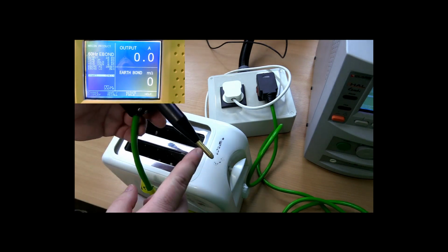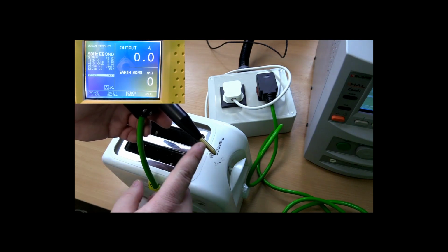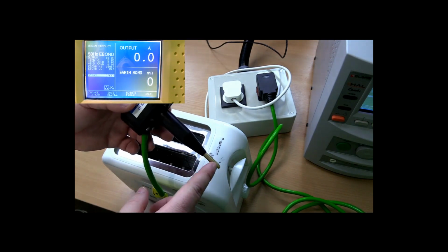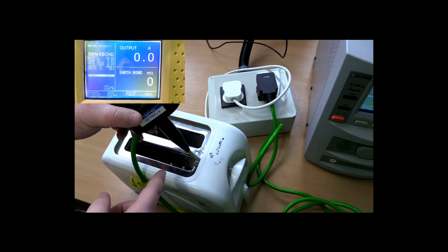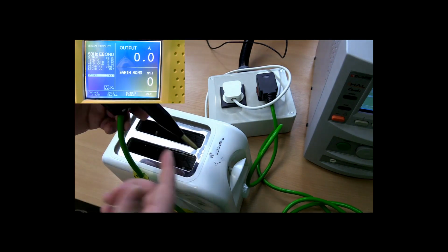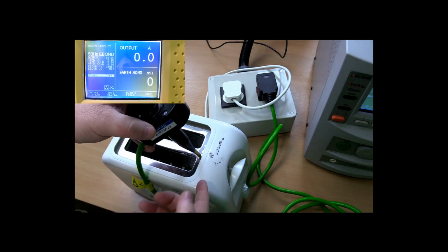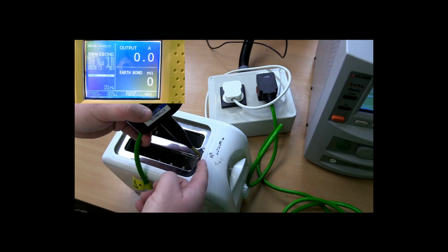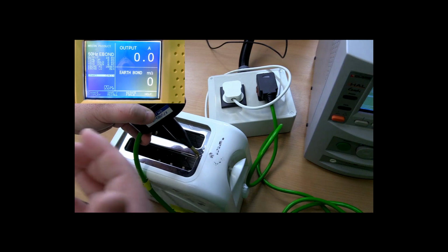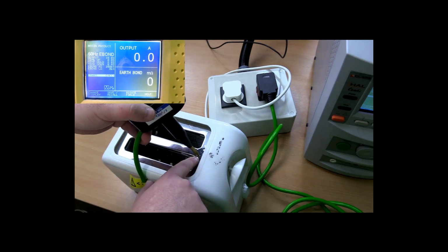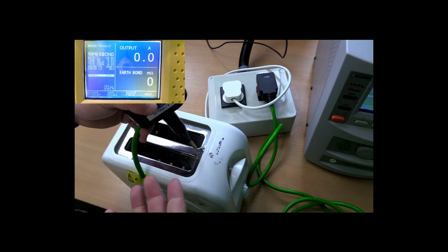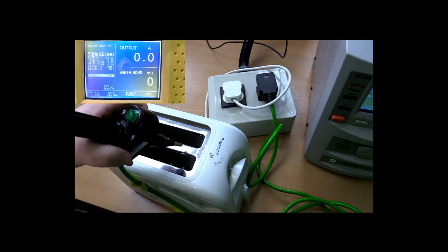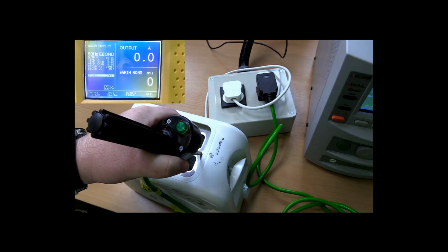So integrated into the test probe is also a start condition. We call it our no burn system. So it allows the operator to press the probe down, press the probe to start via a micro switch, and then maintain pressure so that no sparking will occur between the two mating points. Now that sparking could create some kind of burn marks on the product, and we obviously don't want that for cosmetic reasons. So let's put it on, and we're ready to test.